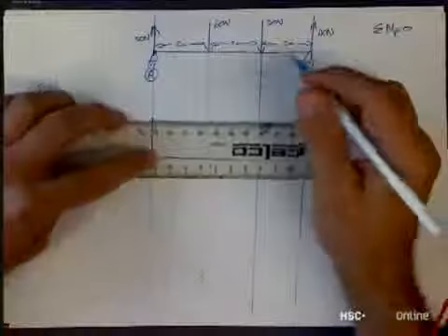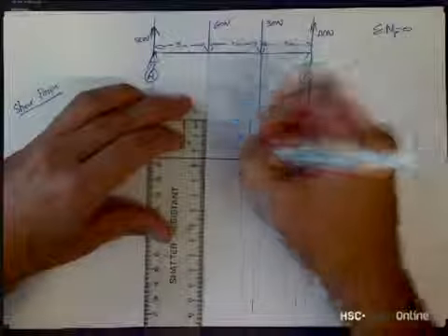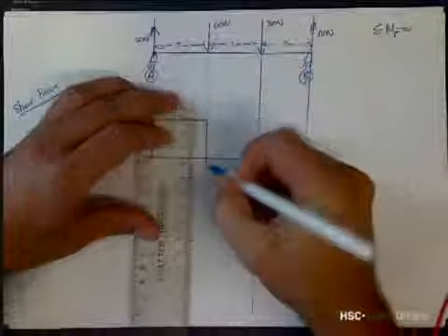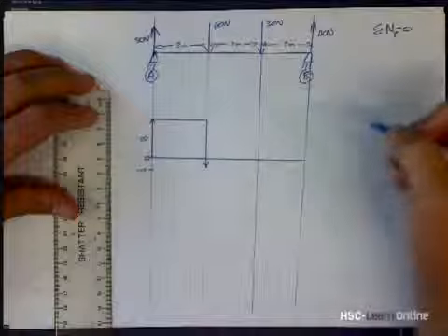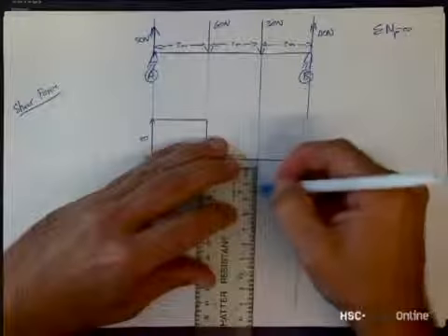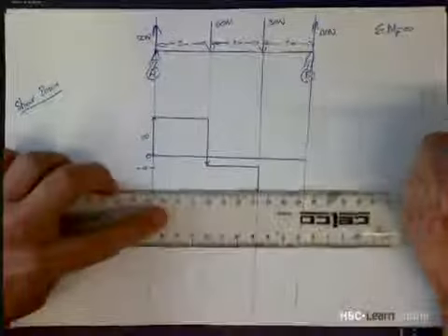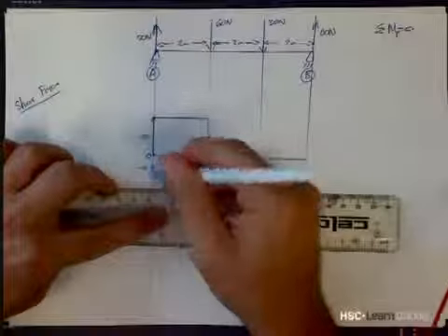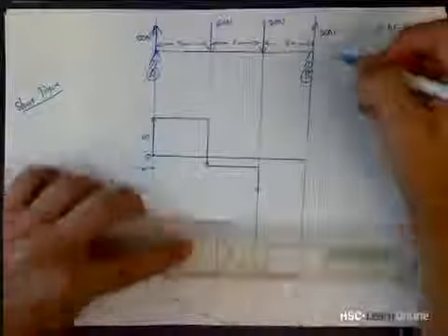For shear force diagrams, you just draw a straight line across to your next force, and I'm going to do 60 newtons down, so that's going down to -3. So 50 minus 60 would effectively be -10. And then again, I draw my line across. Now 30 newtons down, so that's 1.5. If you think about it, this would be -10 minus 30, which is -40. And then of course 40 newtons up.